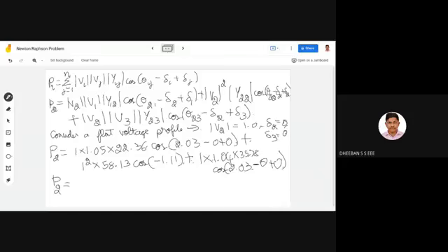I'm just substituting and explaining. The problem is somewhat lengthy, but it is easy to solve. You just try it out. After this P2, you have to move towards your P3. After that, you have to substitute the formula for your Q. Here we won't be sticking with Q3, we'll be sticking with your Q2, since the third bus is a PV bus.